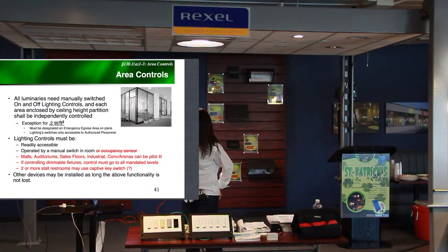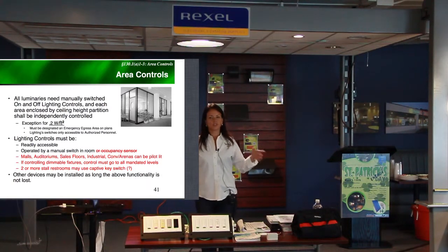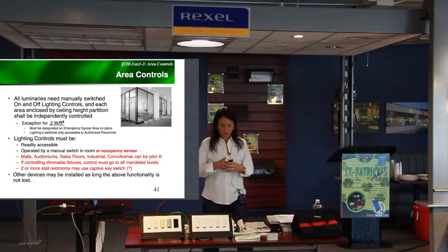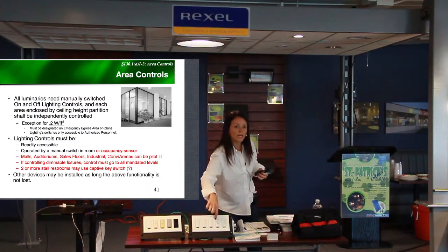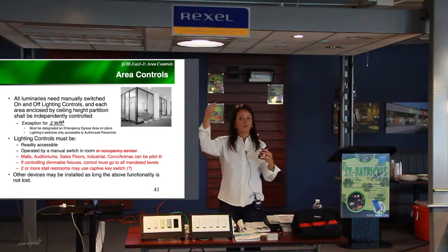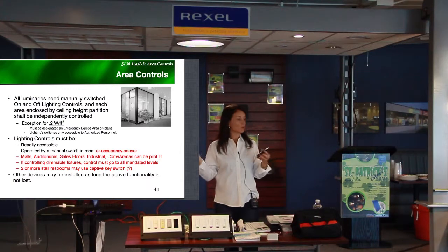For some areas like malls, auditoriums, and large conference spaces, the switch doesn't need to be physically in the space as long as there is a pilot light. A lot of switches you can find in the industry have a little pilot light, and you can engrave the areas, as long as there is a switch for each general lighting control in that space. That complies with code.